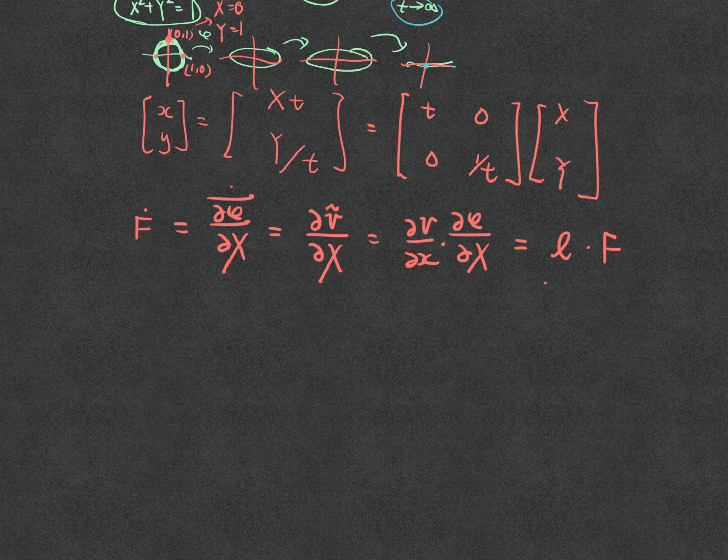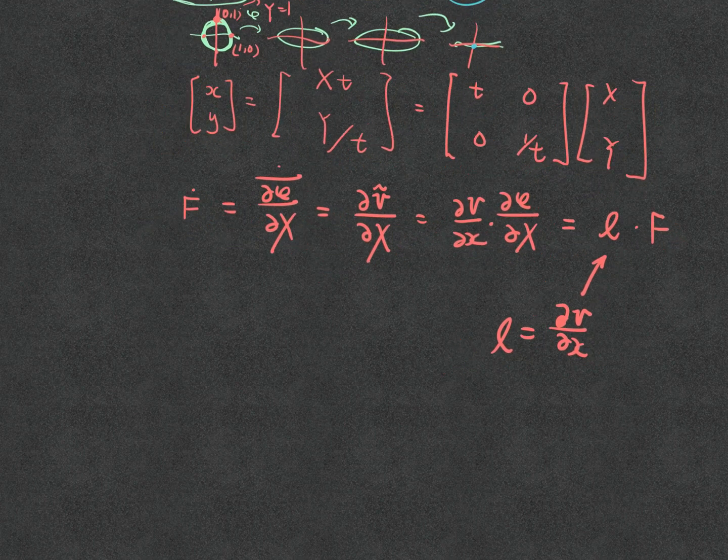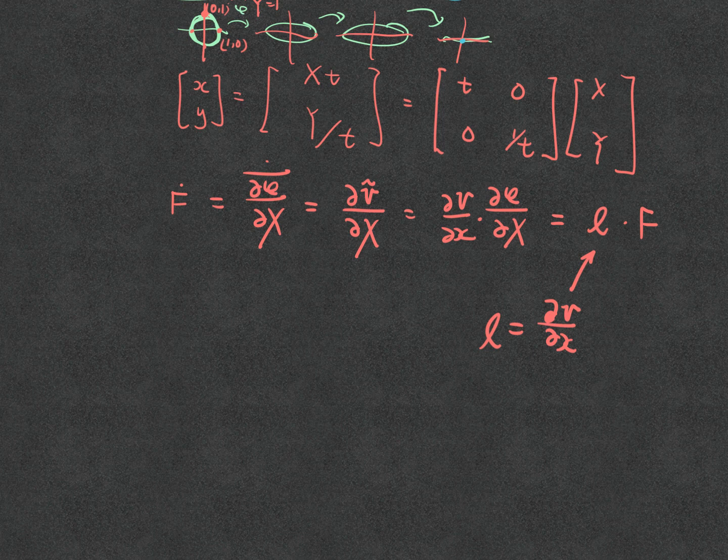Okay, one thing that is very important is that this is called the velocity gradient, and the velocity gradient corresponds to the current configuration. Now there's a long history of that velocity gradient, because sometimes the constitutive law is written as a function of the velocity gradient. Is it true?